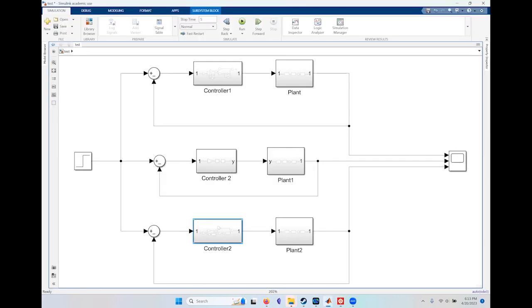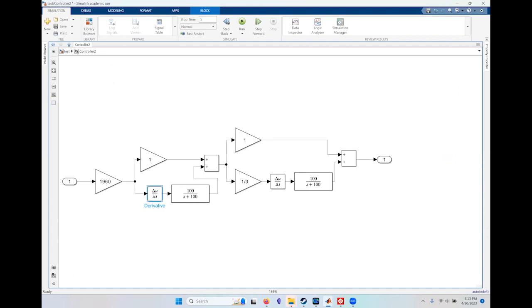However, whenever you try to do this in simulation, this is going to capture any step function, any place where the input or the signal changes instantly. It's going to capture that instantaneous change, and it's going to cause a huge numerical error, because the step is going to propagate.